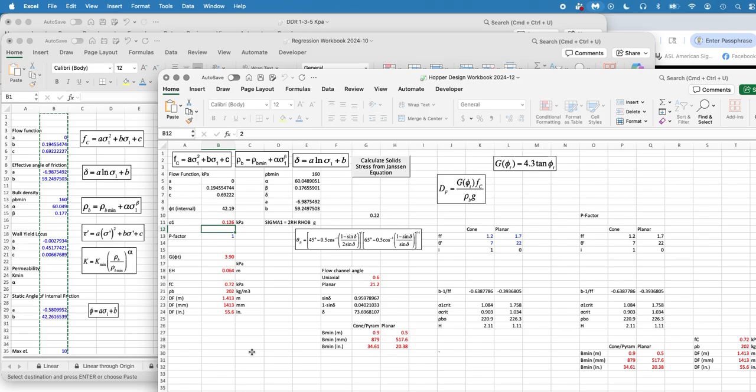So the bottom line is, man, if you have convergence, you're going to be in trouble. I know you have a little bit of convergence in the feeder because the way it looks like, you have the agitator below a converging section. It might reach the agitator because that distance is pretty short, but it's kind of risky. But in any event, what I wanted to do here is show you how to use the spreadsheet. And I hope this is helpful. Give me a holler if you have any questions.